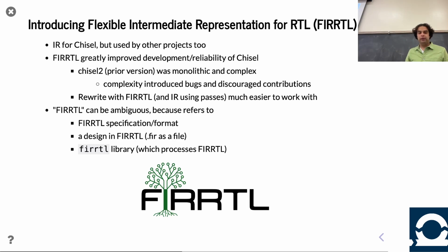And so when you hear me use FIRRTL, both me and the community will often use FIRRTL to refer to multiple things. It's worth being aware that this is multiple things, right? So FIRRTL is the IR, which is a specification format. So there is documentation you read online about what the semantics are, that sort of thing. FIRRTL also can refer to a specific .fir file, an actual FIRRTL file for a hardware design.